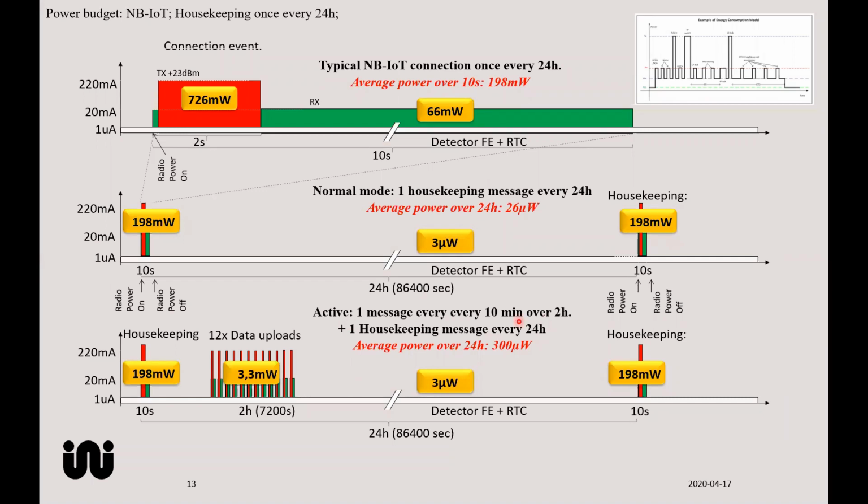On the other hand, when you look into the system design and selecting what technology to use, it might not be possible to do anything else than cellular connectivity. Thus, narrowband IoT might have been the obvious selection. In this case, for this application, we actually have a gateway in close proximity that monitors multiples of these sensors, and that gateway in itself can be connected to the backend over some cellular network. So, for this specific application, narrowband IoT was not the obvious choice.